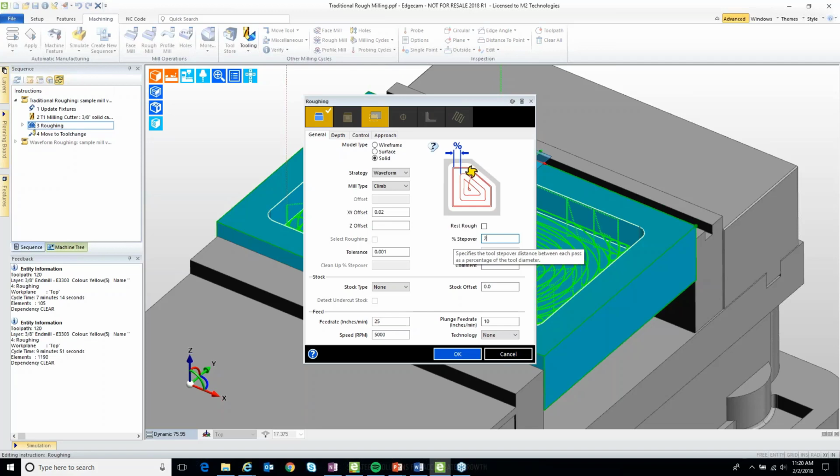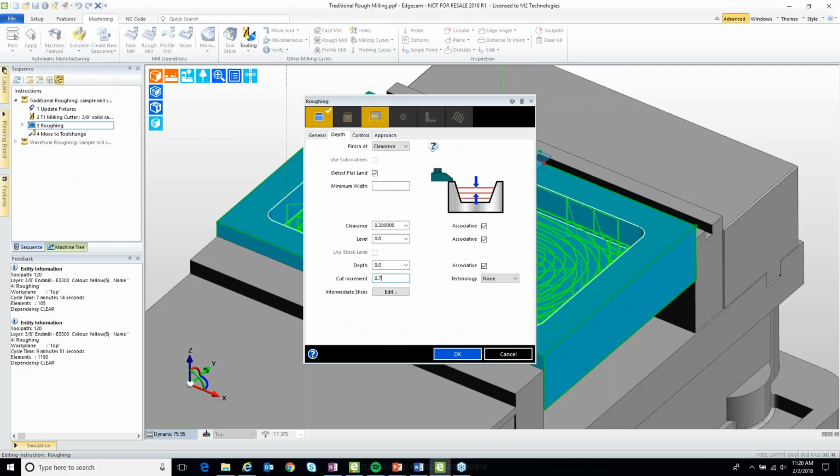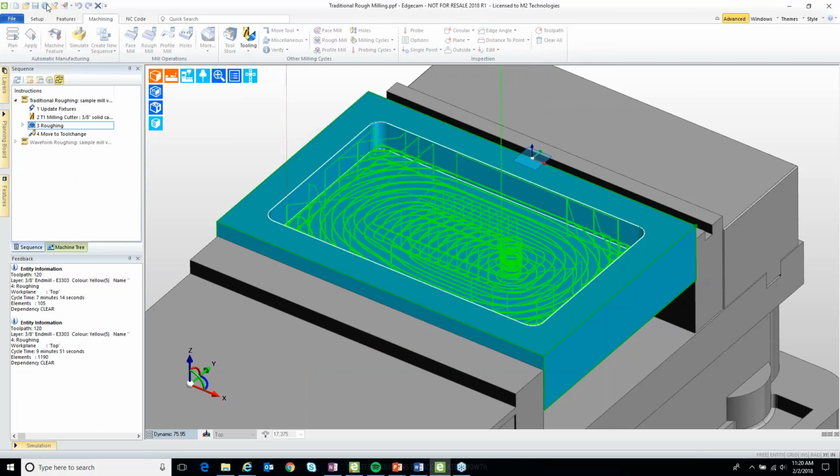Let's tell the software to look up good high-speed cutting data from our tool library using data we've plugged into there. So the speeds and feeds are optimal for a 20% engagement in this case, and what the tool is capable of in depth in this stainless steel material, or this tool steel, I should say, 700 thousandths of an inch. So with those cutting parameters in place, now let's go look at what the cycle time is.